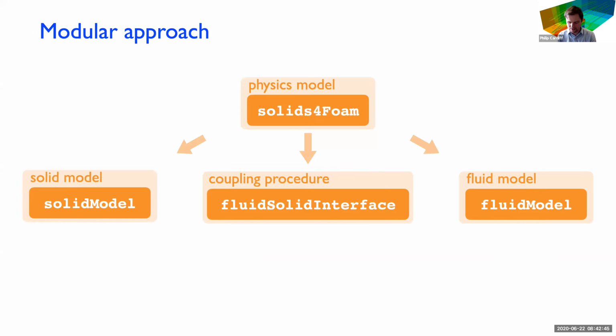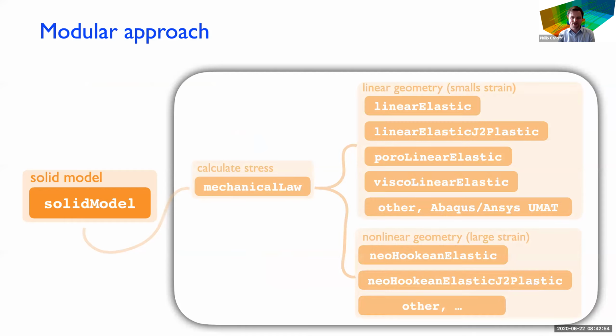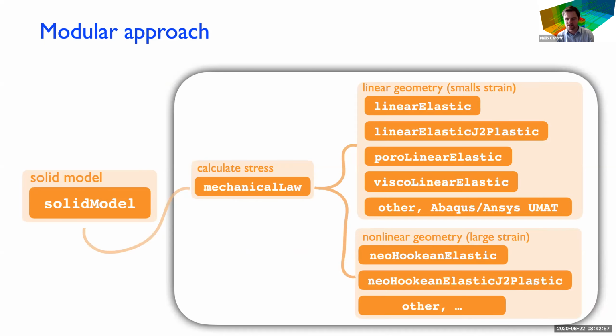And in fluids, often the critical thing to get accurate predictions can be the choice of turbulence model. So an analogy of sorts in solids is the constitutive model. The turbulence model in fluids is giving you your definition of stress, or Reynolds stress or deviatoric stress. In the same way, the constitutive model in solid mechanics gives the definition of stress as a function of your velocity or pressure, or more commonly in solids, your displacement field. So you might be familiar with linear elastic, or Hookean elastic, it's called. That's just the most simple approach. But you might have plasticity, you might have poroelasticity, you might have viscoelasticity, etc.